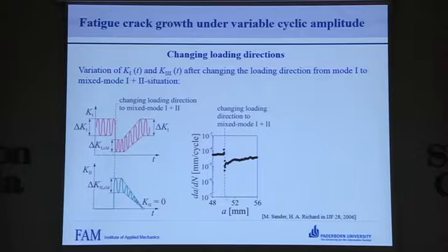In the first test series, the loading direction was changed after a crack growth of 3.5 millimeters under mode 1 loading condition into in-plane mixed mode as well as spatial mixed mode situations. The R ratio here was constant at 0.1.